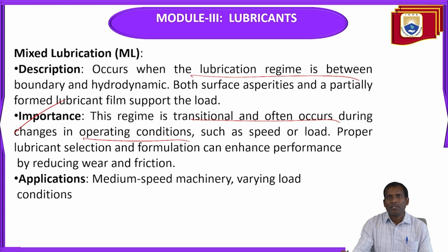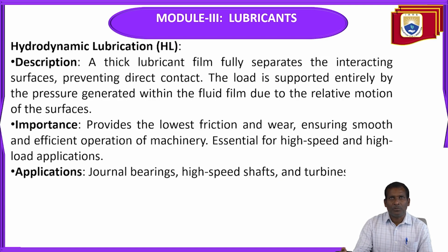Proper lubricant selection and formulation can enhance performance by reducing wear and friction. The applications are medium speed machinery and varying load conditions. Wherever there are varying loads and medium speed machinery, mixed lubrication is suitable.